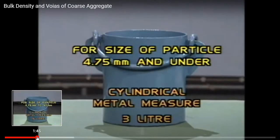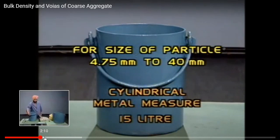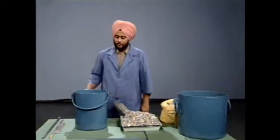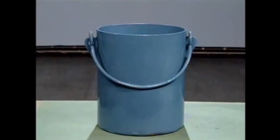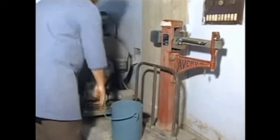Metal measure of capacity 3 liters is used for smaller particle sizes. For size of particle 4.75 mm to 40 mm, the cylindrical metal measure of capacity 15 liters is used. For size of particle 40 mm and above, the cylindrical metal measure of capacity 30 liters is used. To start the experiment, choose the metal measure of desired capacity depending upon the size of the aggregate. In this case, since the size of the aggregate is 20 mm, the metal measure of 15 liters capacity is used for the test. Take the empty weight of the metal measure. So here you can see, first what we will do, we'll take the empty weight of the container.